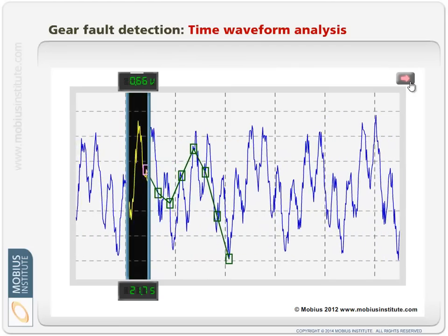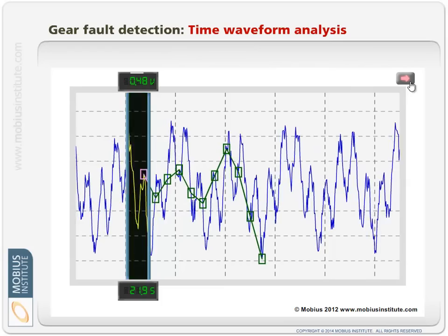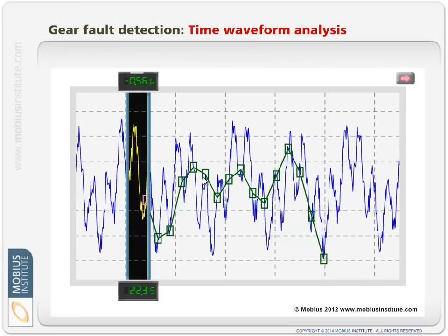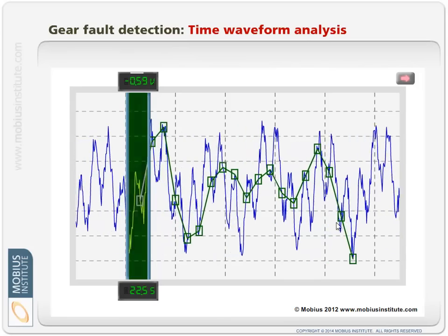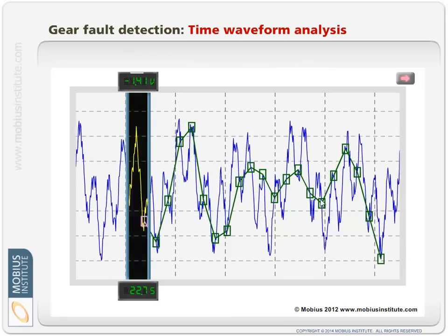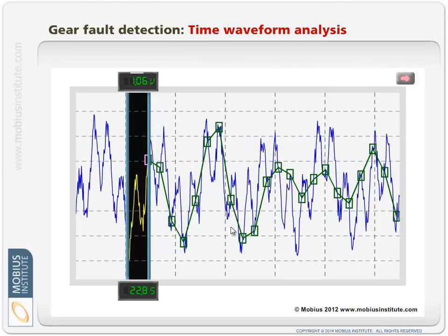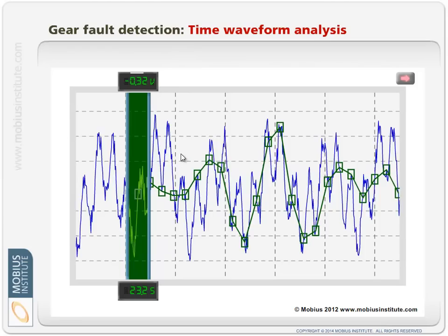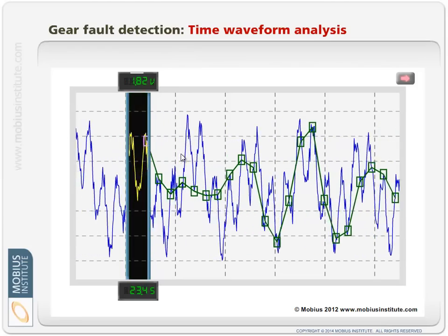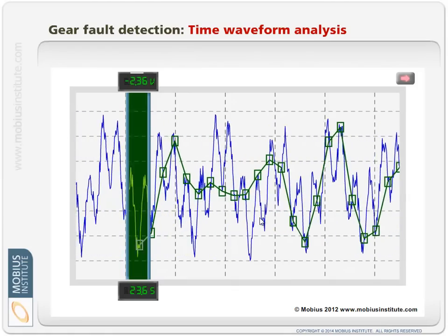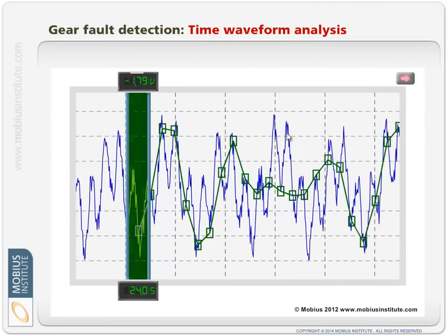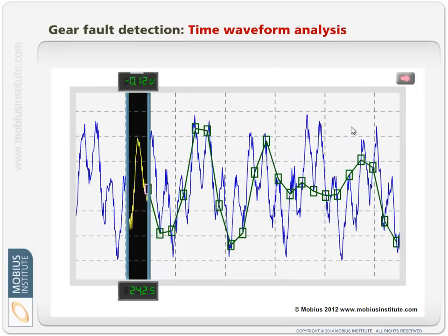etc. You can see them. But if the sample time, the time between each one of these samples, is too slow, you can see that the waveform, this green trace here, is what the analyzer will remember and then put through the FFT and display to you in a time waveform window. Well, this green trace has nothing to do with the real vibration, does it? It's obviously poor. We are obviously sampling too slowly.